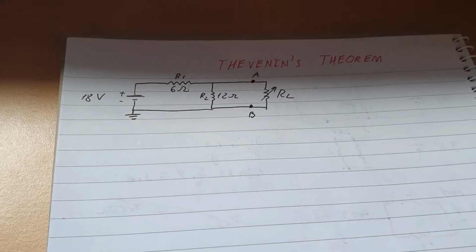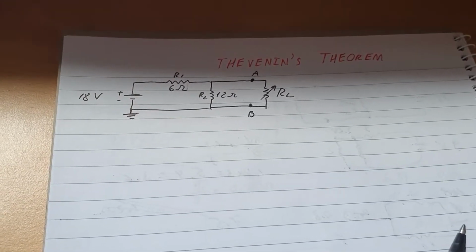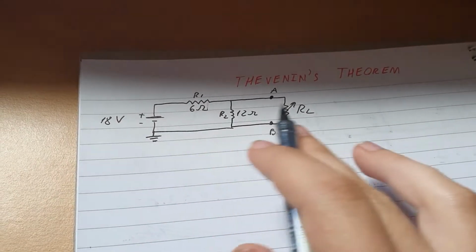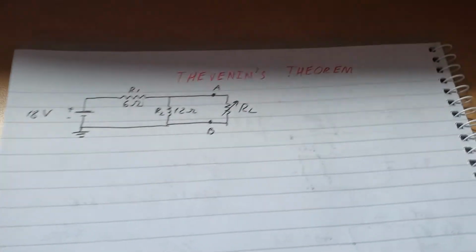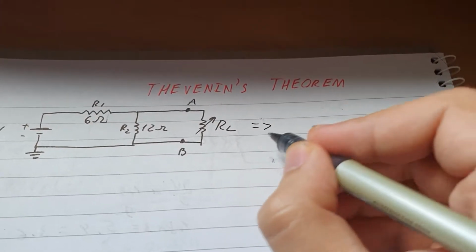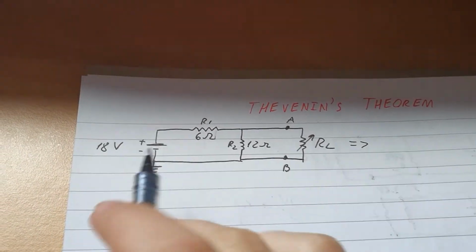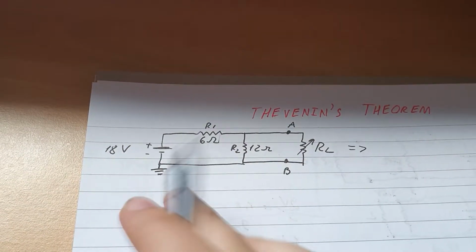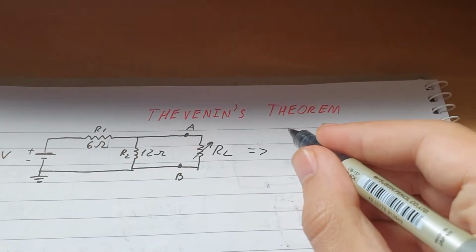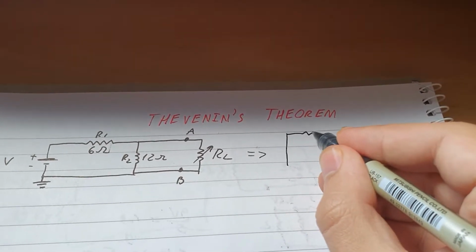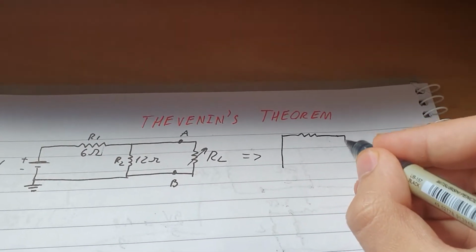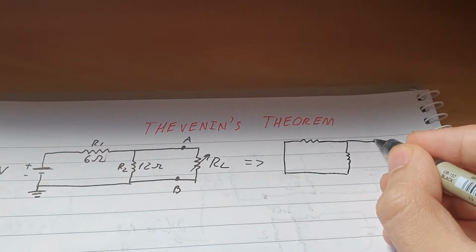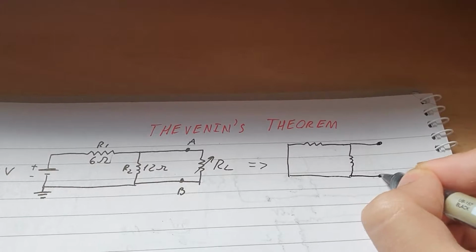The first step is to separate the voltage and the resistors. Our next step is to, like in superposition, make the voltage sources or current sources a short. Then we get something similar to this. This is one resistor, this is the other one, and here is the opening, there and there.